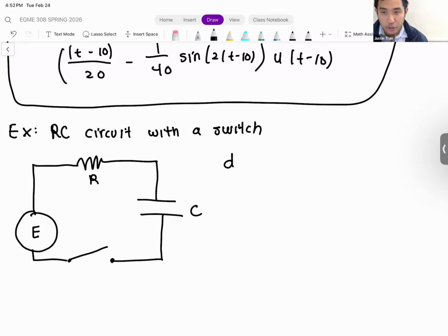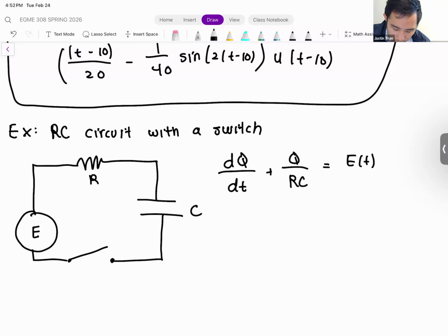So our differential equation for this: we're going to be looking at the charge on the capacitor. So the differential equation is dq/dt plus q divided by RC is equal to E(t) divided by R, where E(t) is equal to...